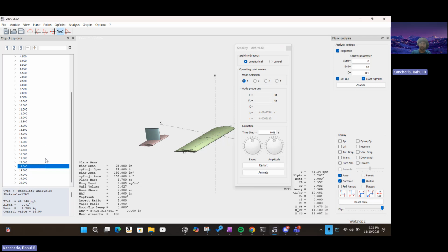And how do you know that your cruise condition is good? You have an angle of attack that is close to 0, and it gives you data around your cruise condition, and then a CL/CD where the closer to 1 the better is the best way to say it.